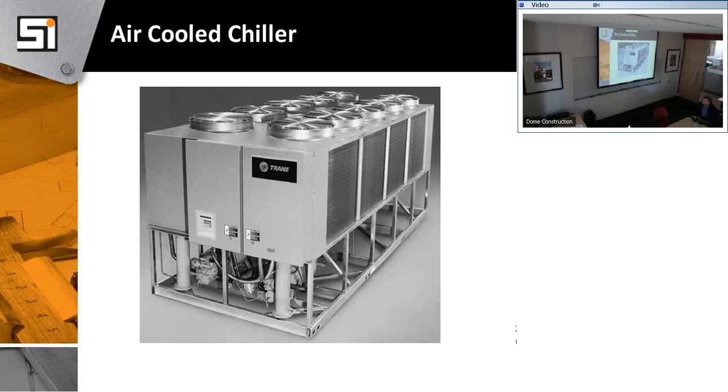Again, these are clean, right? That other one, I had to place a cooling tower, I had to get a drain, I had to pipe water over to it, we had a bigger footprint. So this is just a packaged chiller in a sense. The nice part about these, we could set them wherever and just hook up. I don't have any condenser water piping, I have no water treatment, I have no drain, I just get to hook up two pipes and deliver chilled water. They're not as efficient except on cost. Cheaper.